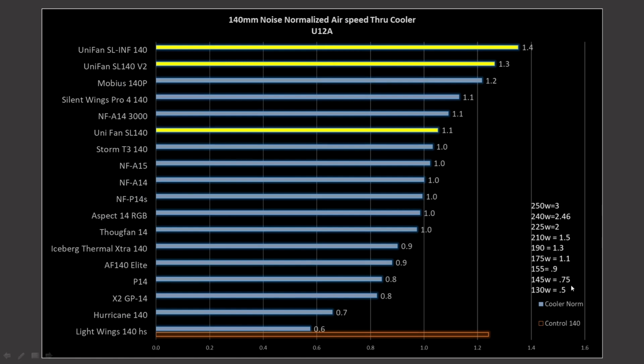First, a little bit of a note. This over here on the side here is a wattage versus airspeed. I did a number of tests on my CPU air cooler to equate what wattage equated to what airspeed traveling through it, letting the CPU hit thermal max, so steady state wattage, and then I slowly decreased the PWM fan signal down to its minimum level to get a wattage versus airspeed. This is an estimation, and I've calculated it to be accurate within plus or minus 5 watts.